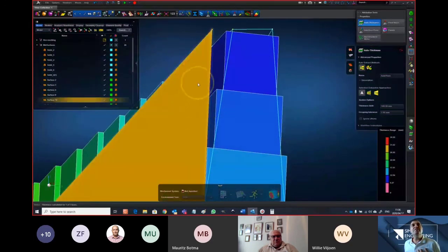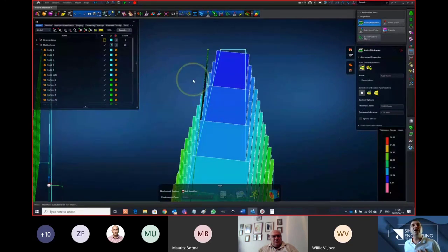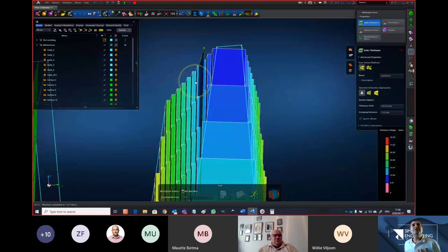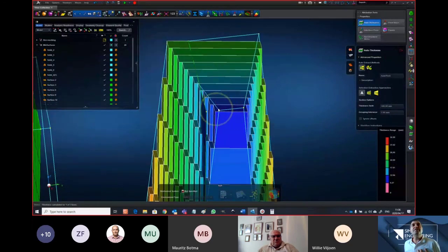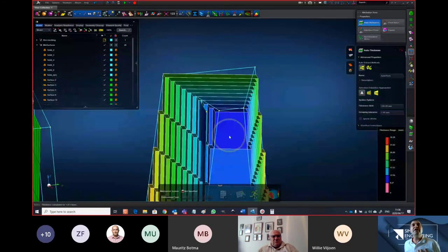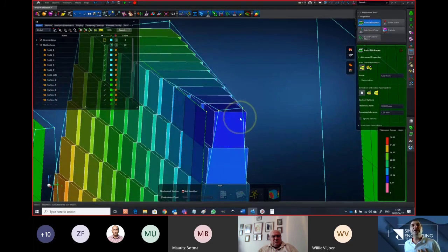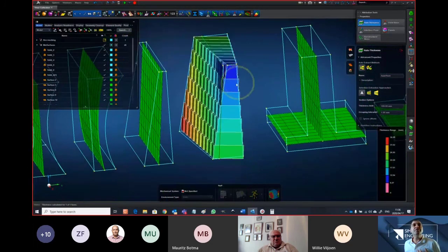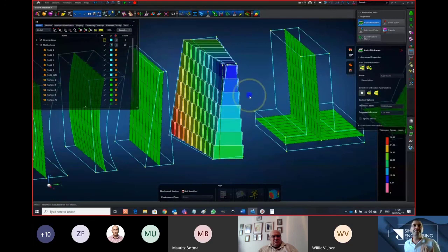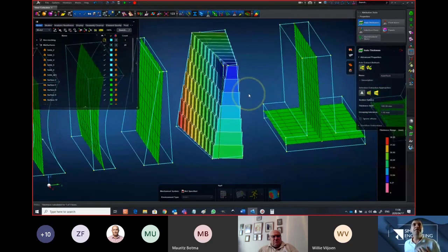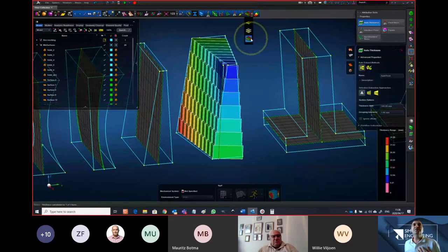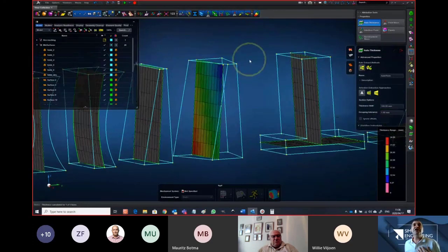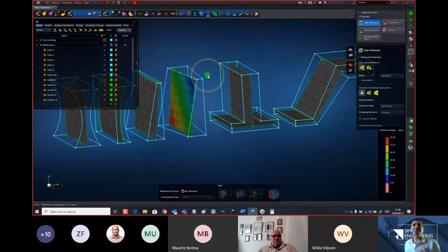So even though the physical shell element is outside the solid, the property was still assigned properly, providing the thickness of the solid in that area, as well as the offset property. So it will mathematically work exactly in that way. So using the visualization tool is also a nice way of just checking how it was done.